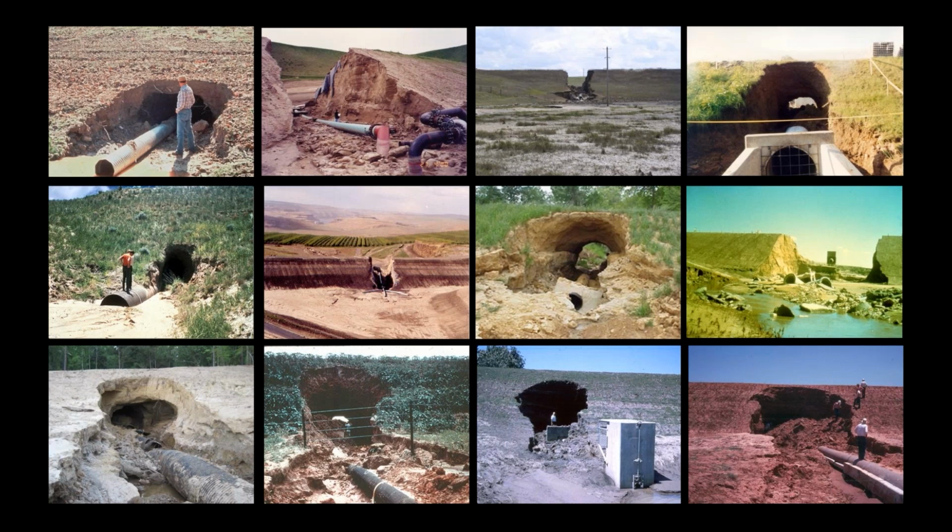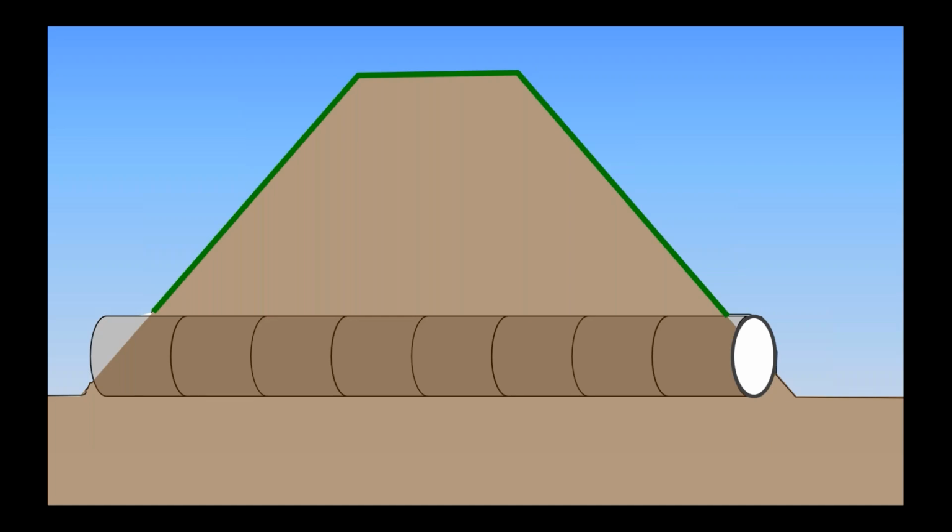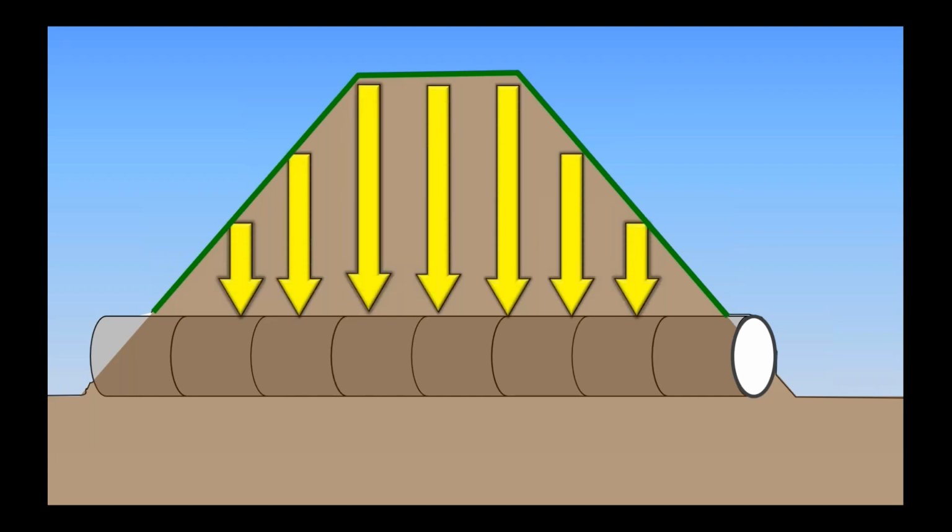There are a couple of reasons why you can get seepage along a conduit. And the most common reason, I'll show you a schematic here in just a bit. So here is a conduit that was placed through the embankment, so that's the penetration. And then they place the embankment below, on the sides, and above. And we also have the loading that's shown by the size of the arrows. So we have more load at the maximum height of the dam than we do at the ends.